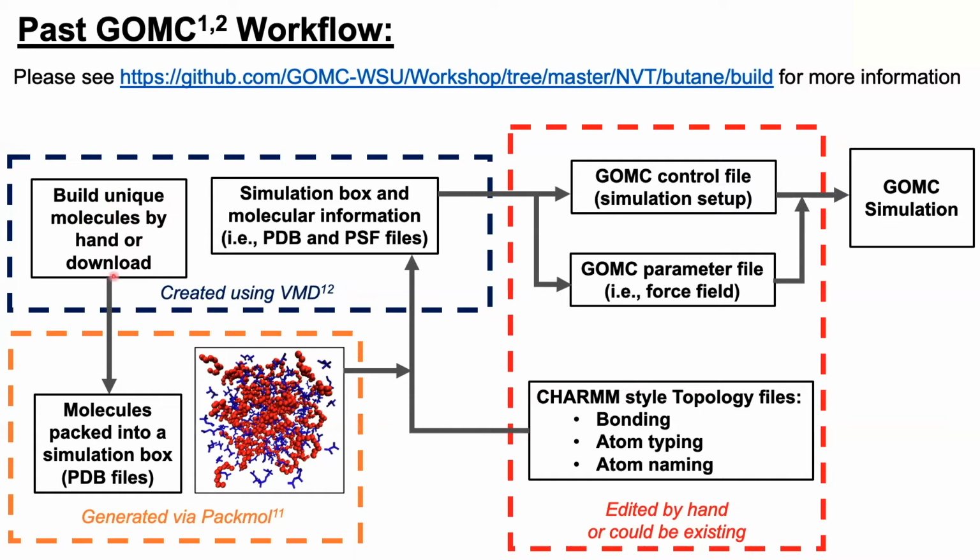And then basically you use those unique molecules, you write a script that PackMol can read, and then you use PackMol to pack it in a simulation box. So you can see I had two different types of molecules here, the blue one and the red one, and now they're packed into a box here of my specification of number of molecules.